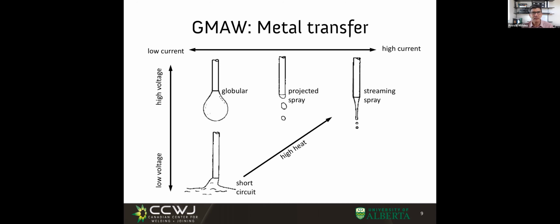So an interesting thing about welding is that although we can weld just because we have a torch in our hand, understanding the welding is super deep. And in the first class I mentioned this big name, magnetohydrodynamics. That is what explains this transition from globular to spray. We don't need to do big equations, but it's good to keep in mind that it's just the intensity of the current that creates these electromagnetic forces that squeeze the electrode and make the droplets smaller.